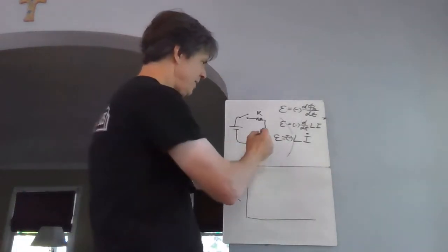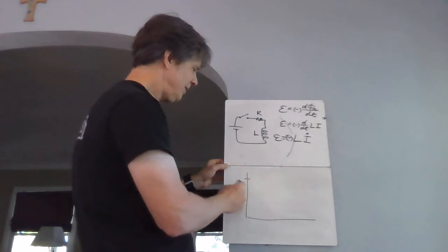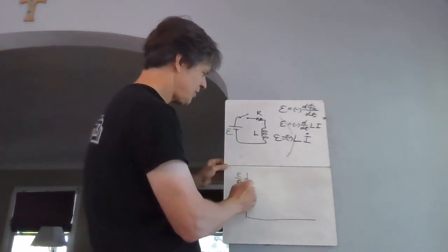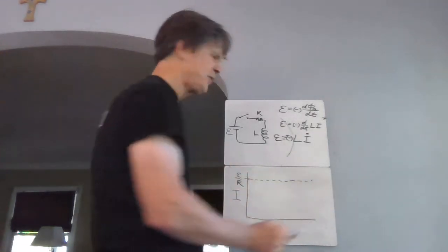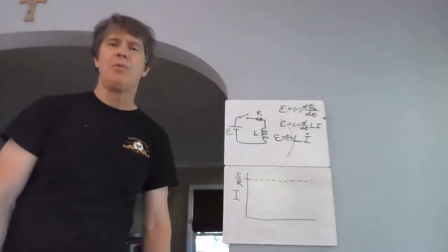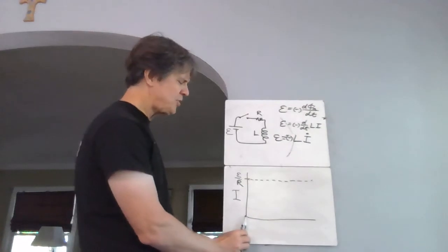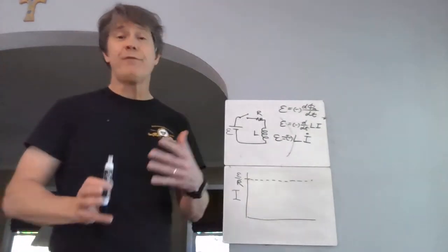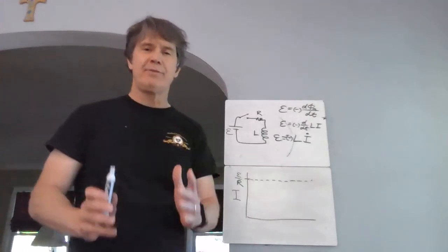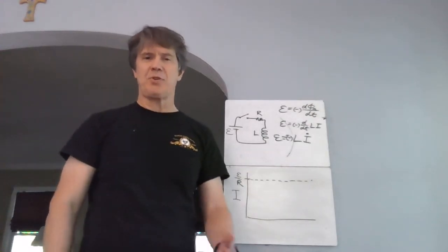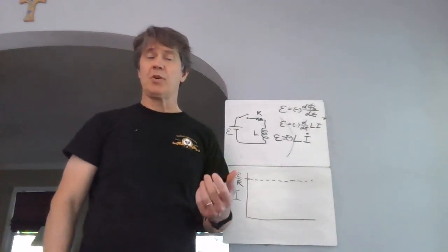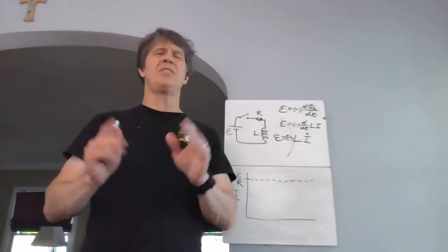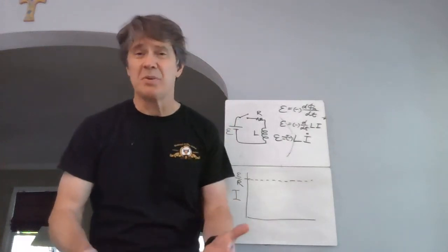Goes around the loops. And it has an inductance L. And the final current would be E over R. That's the current you'd think would happen in the first place. But the inductor won't let it, because when the current tries to instantaneously jump up to that value, the inductor fights back. At first, it fights back every bit as hard as the battery is trying and produces no current at all. But as the change slows down, the thing calms down. You fight the change, but you kind of get used to it.